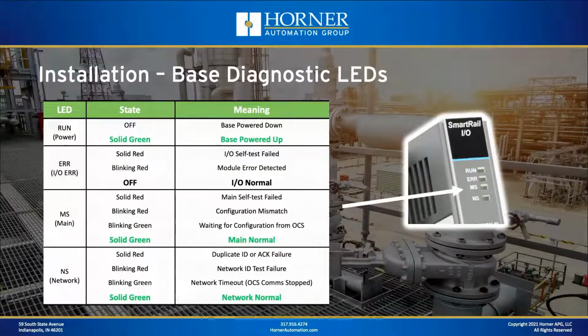But what I did do, in slightly larger print and in bold, was highlight what the desired states are. And that effectively is solid green for run, MS, and NS, and you want the error light to be off. All right, so if that happens, then everything's good to go. And we're also going to cover the diagnostics and kind of the real-world demo here in a few minutes as well.